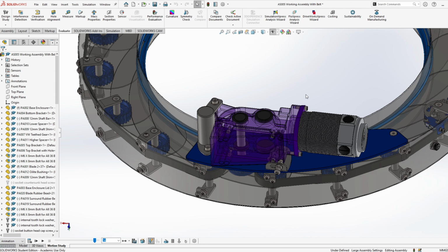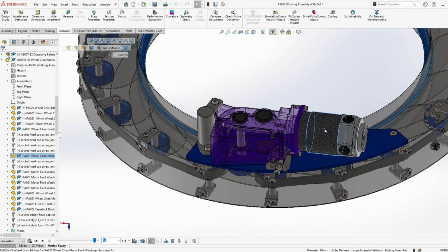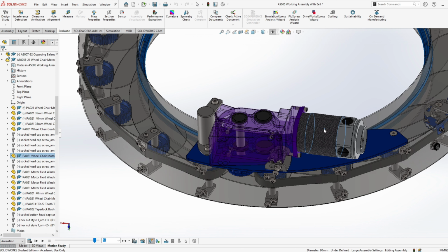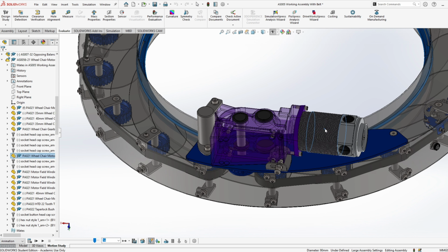I will do a wee demonstration here to show the tensioner mechanism in operation. So if I grab or select the motor here at this point and move it inwards and outwards from the centre of the aperture, we can see how this tensioner bracket glides whilst the adjuster stud makes use of the slotted hole during the adjustment stages. Also, notice how the gearbox pivots on the bollard type hinge bracket to the left of it.